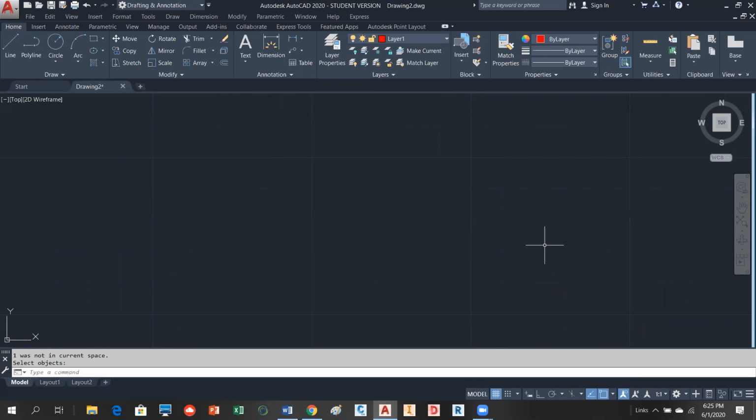All right, so one of the things that's very convenient in AutoCAD is to be able to work in units. So units come in 2 types in AutoCAD. We have linear units or distance type units and angular units or angle type. To get to this command, the easiest place to do it is to just type it in.